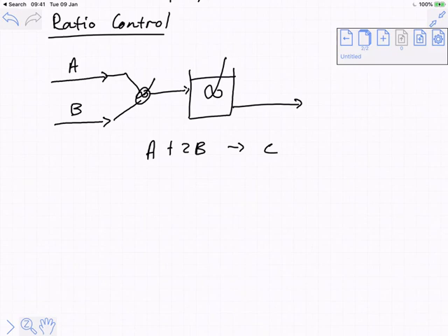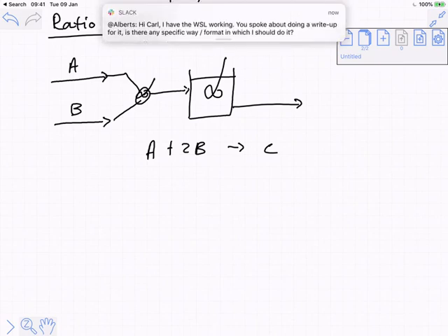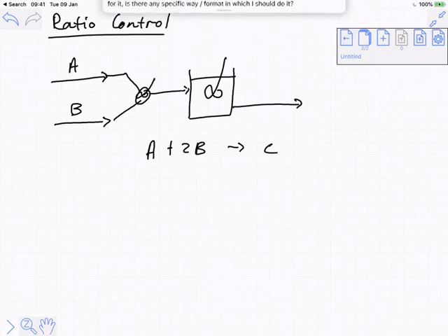But once you boil all of that down and you've done all your unit conversion, you can say, well, from back calculating from a ratio of 1 to 2 on A to B, that means I need a ratio of 4.32 cubic meters of A per second to 1 cubic meter of B, say, right? These things can happen.